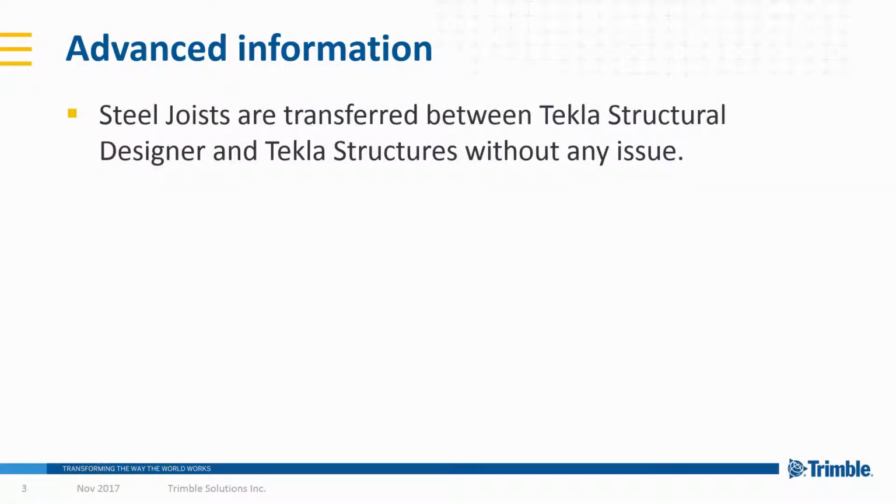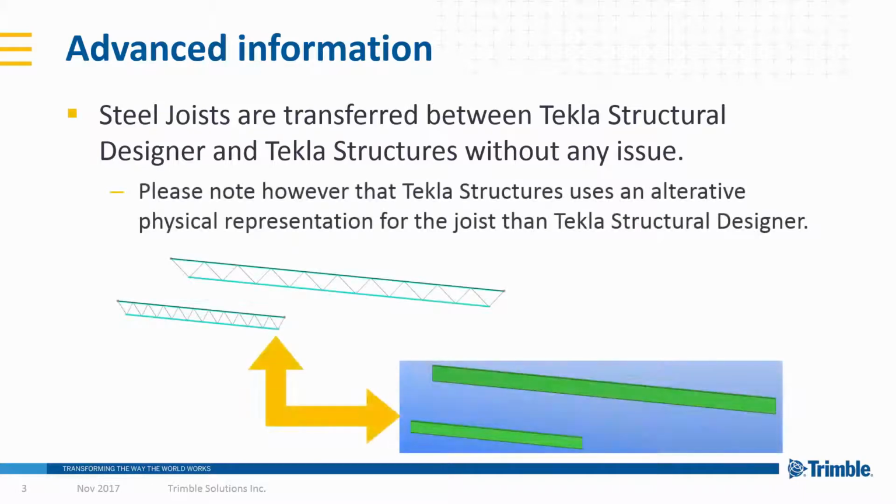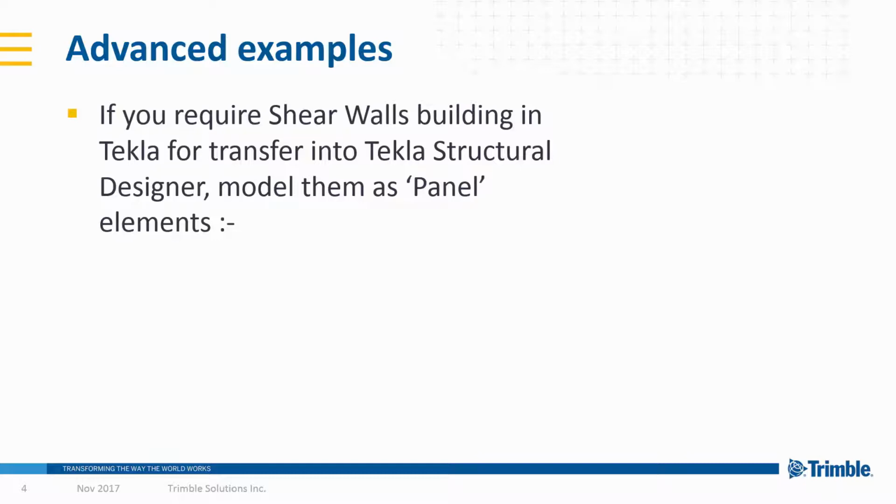Steel joists are transferred between Tekla Structural Designer and Tekla Structures without any issue, and can be round-tripped without any problems being encountered. Please note however that Tekla Structures uses an alternative physical representation for the joist than Tekla Structural Designer. For wall elements, we can confirm that shear walls modeled in Tekla Structures will be transferred to Tekla Structural Designer provided the correct settings are used.